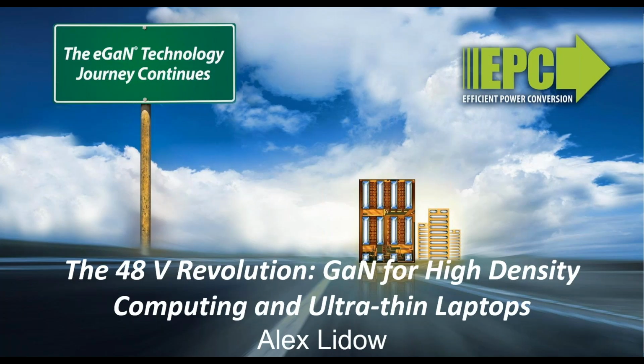Silicon-based power conversion is not just keeping pace. Due to the significant performance improvements that GaN offers, a fundamental shift in the server architecture is possible, and that will significantly increase efficiency, shrink size, and reduce system cost. This new architecture reduces energy losses by greater than 30%. And we'll look at this shift and explore the pros and cons of various topology options to achieve the highest power density solutions for 48-volt power in data centers, including buck, LLC, and switch capacitors.